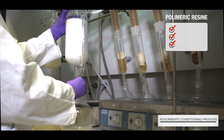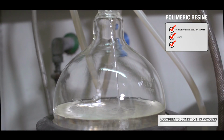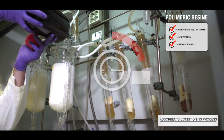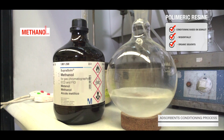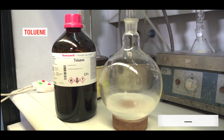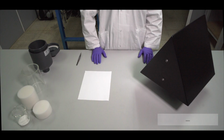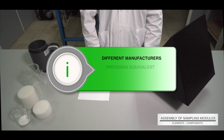In the case of the polymeric resin, conditioning consists in sequential Soxhlet extractions during extraction periods of 24 hours each, using organic solvents. First methanol, then acetonitrile, and finally toluene. Once conditioning is accomplished, sampling modules assembling can be performed. In general, a number of equivalent active air samplers are commercially available and supplied by different manufacturers.